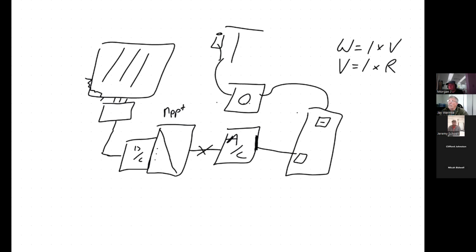Then we get into the third equation, which is a variation of Ohm's law: voltage drop equals amps times resistance times twice the distance divided by 1,000 feet. And why are we doing twice the distance divided by 1,000? It's because we're given resistance in ohms per 1,000 feet.